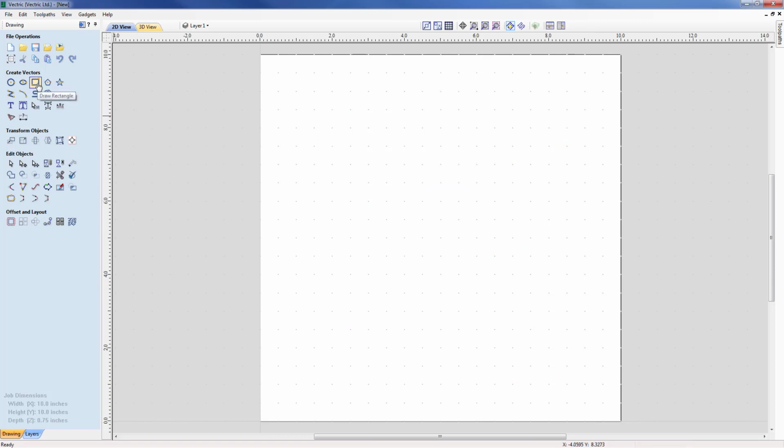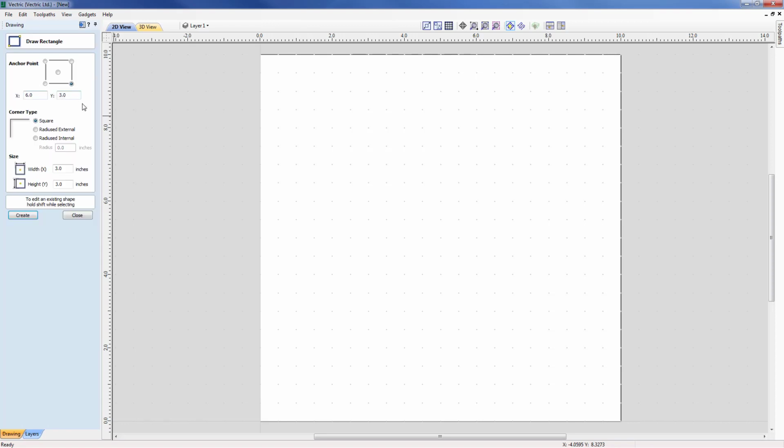So I'm going to come across now and click on the draw rectangle, which will open the form. I'm going to move into my workspace and specify my first corner. So I'm going to click on that corner, and I'm stretching, of course, in X and Y. And I can, if I want to just have a square, type on the keyboard just one value and return, and that will give me a height and a width the same, i.e.